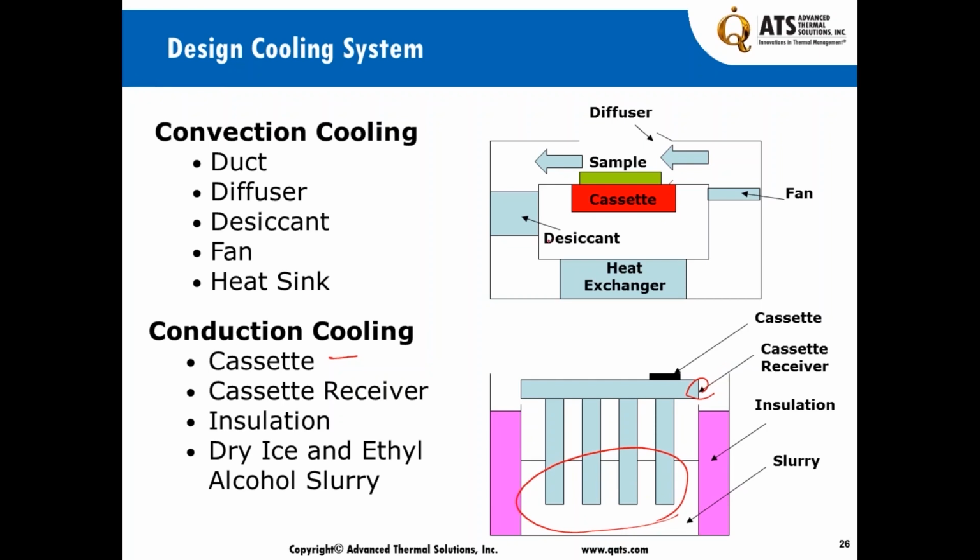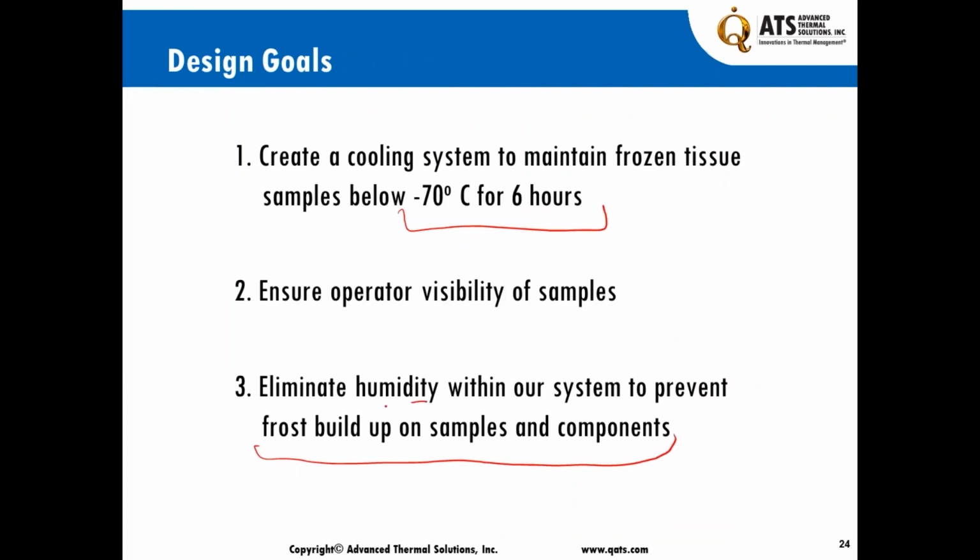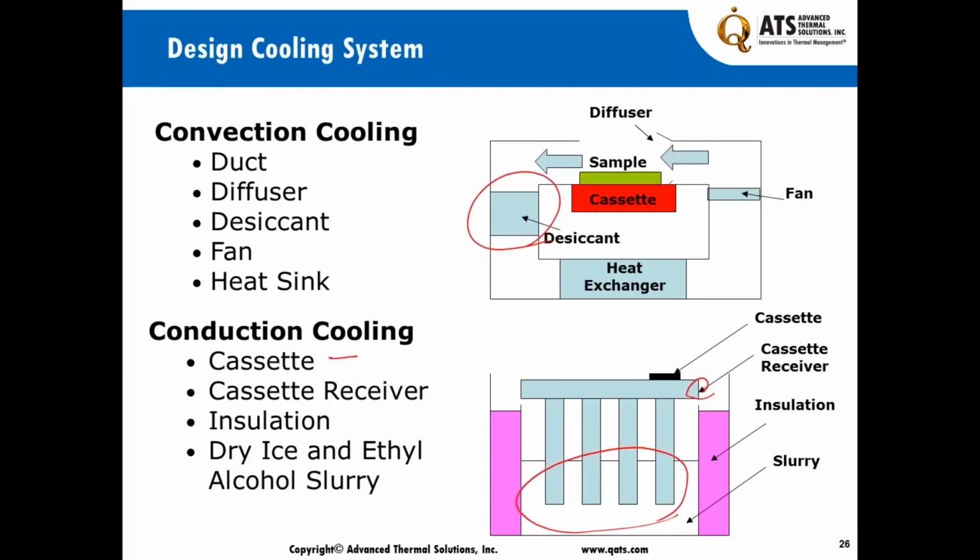But there is airflow and also heat exchange that has to take place in order to make sure that's happening. The desiccants that you see here are there to extract the humidity out of the air. And remember, one of the conditions that we had was no humidity. The humidity factor was the one that we had to minimize. And the way to minimize it, you can obviously run a dryer at the noise and the cost, but desiccants work very effectively, and the cost was also an issue that we had to manage.